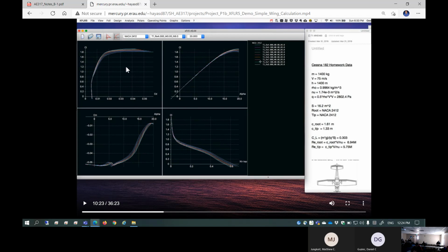So you're going to compute a bunch of data. This is basically called a 2D airfoil database, a polar mesh. Mesh means you're going to compute over the range of Reynolds number and the range of angle of attack. So you have to do this first for your design range. The 4 million is this dark cyan, I would call it. That pinkish color is about 6 million, and that lighter one, light blue I guess, is 8 million.